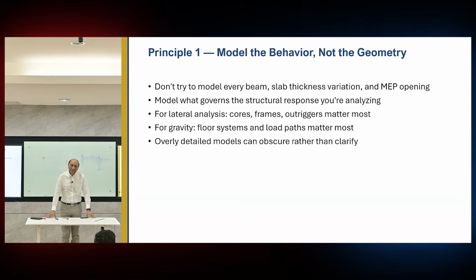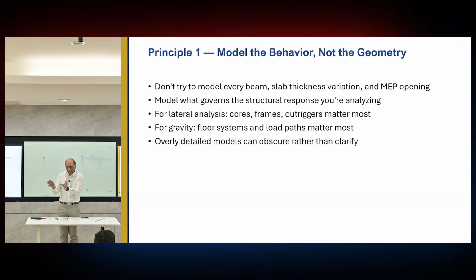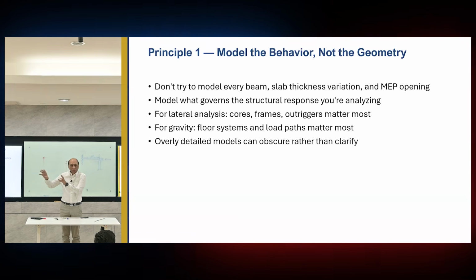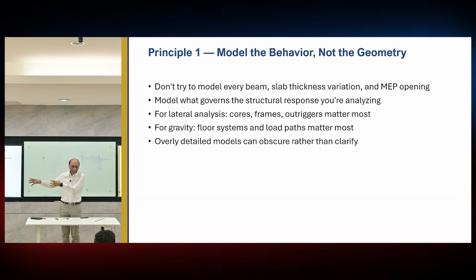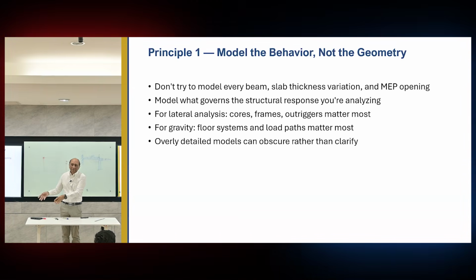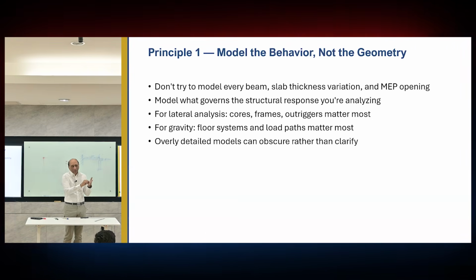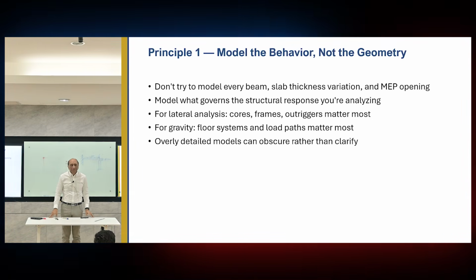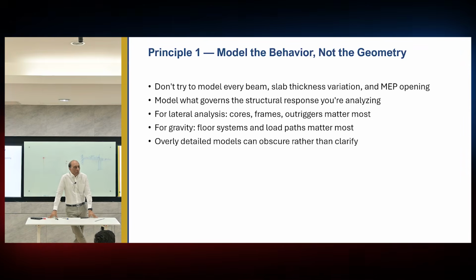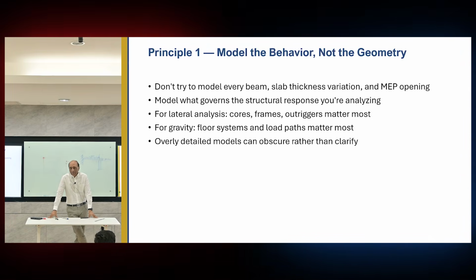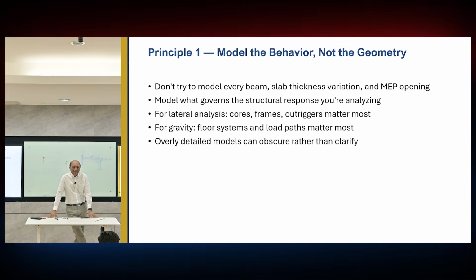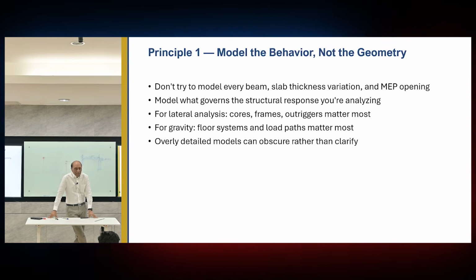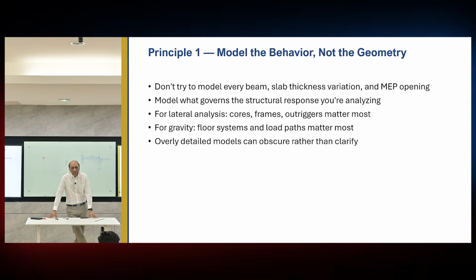Because previously, ETABS or SAP was a separate program. AutoCAD was a separate program. So whatever architects do in AutoCAD is their business. When you come to SAP, you have to make your model by yourself. Every element, every node has to be drawn by you. So you will choose to draw only things that you need for the analysis, and you will ignore things that are not related to you. And you make a very clean, minimal, proper model, just enough for you.